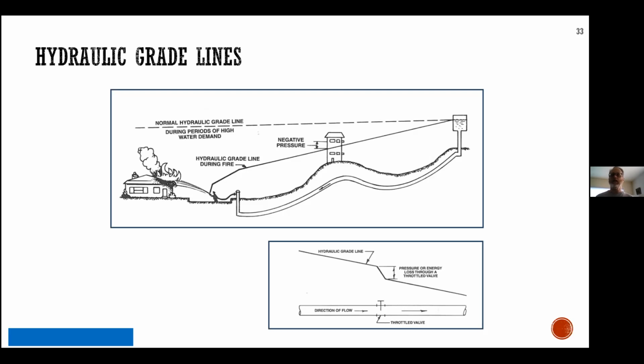So again, whether we stuck a clear plastic tube here and here and here, all throughout the system, we could actually create a visual representation of that grade line physically. Most of the time, we simply do it with a pressure gauge. And that is why it's really critical for operators to see the readout on a pressure gauge in kPa or PSI, but kPa, and actually translate that into available energy.